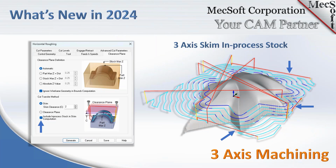But what this enhancement does is it also introduces the in-process stock in the computation. So if you had a roughing operation done previously and there were chunks of stock where you have the arrow on this picture, let's say there was an in-process stock on the way.